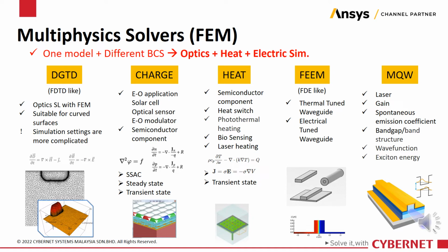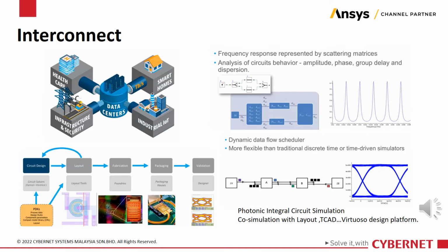For example, to design a traveling wave Mach-Zehnder modulator, it is necessary to simulate the modulation curve of the carrier density to the effective index, and the optical and radio frequency modes in fiber. There are also characteristic parameters of the structure, such as the capacitance and reactance, which need to be brought into the circuit system simulation. After designing the components, Lumerical provides a system simulation interface such as SPICE, called INTERCONNECT.